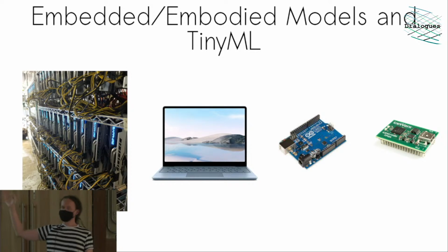The Arduino is great, but it's not powerful enough for what we want to do. So I'm looking at these. This one on the right-hand side is an FPGA, a field programmable gate array, which is a reconfigurable computing system. The advantage of these is they're super fast, so you can do real-time audio processing with them. Disadvantage is they're just a bunch of logic gates, so they're quite difficult to use. You have to program them in this weird programming language called Verilog, which is really tricky.